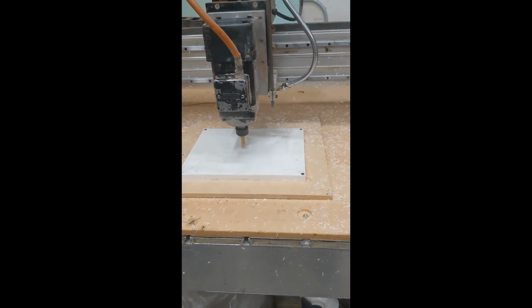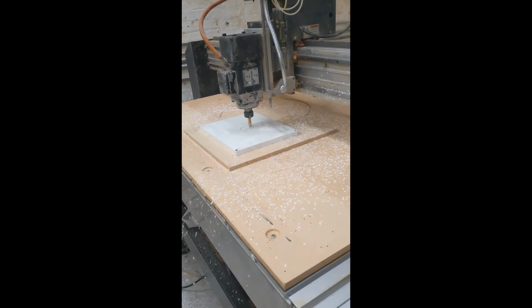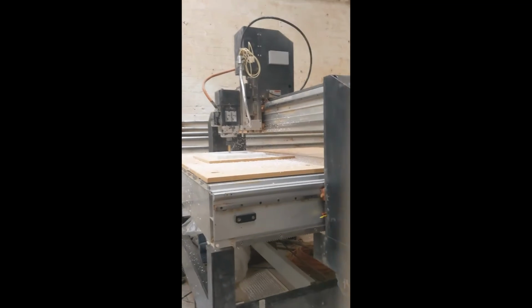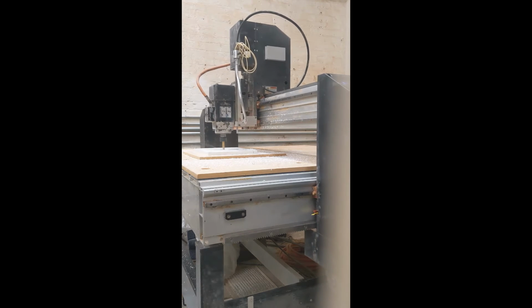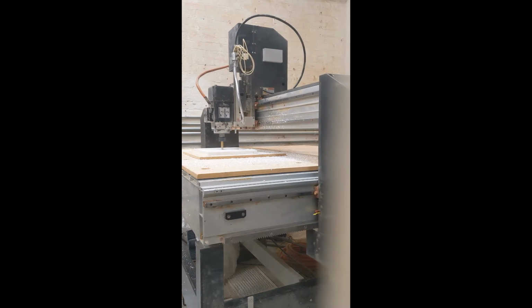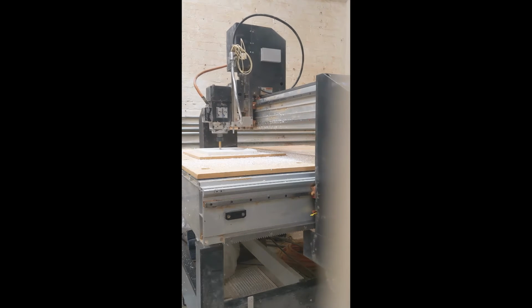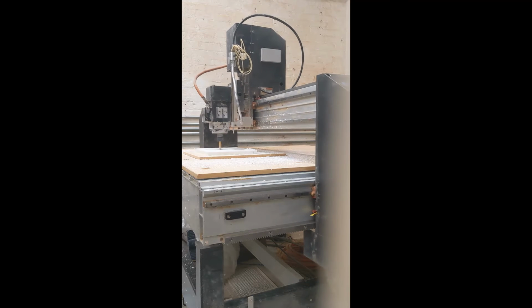And if you post things that you can put, there's no harm in most materials posting things out at like half the speed they're supposed to be, and then doing a feed override up to like 200%. Just give yourself enough room so you can get as high or as low as you need to be. But it's a good way to figure out the correct feed and speed for a material.